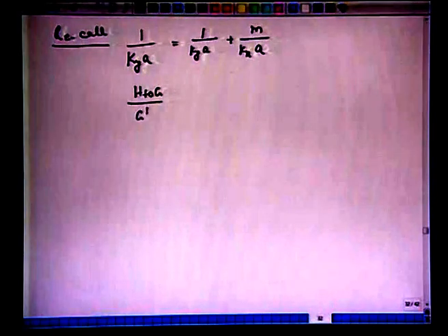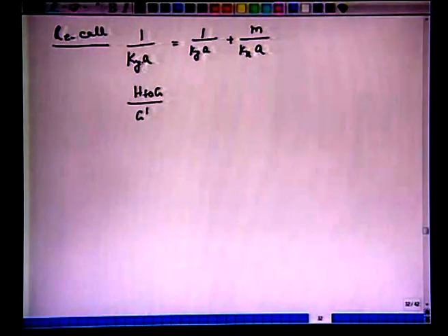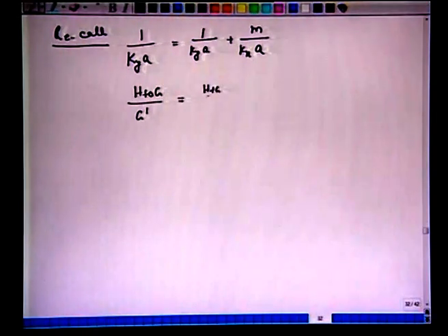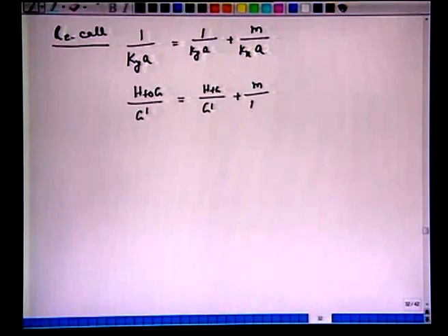Okay. So, just to recap here, if you recall again, we had the overall mass transfer coefficient capital Ky a in terms of the individual gas film mass transfer coefficient plus m, the slope of the equilibrium curve, times kx a, and then we can write HTOG. So, this is the definition we wanted to point out here, that HTOG equals G prime over Ky a, which is HTG, over G prime plus m, and kx can also be written in terms of kx a, L prime, HTL.